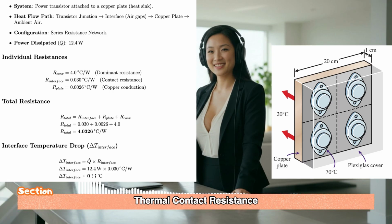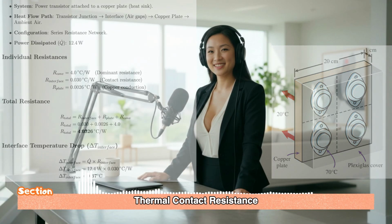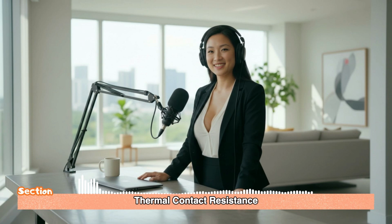But look internally. The interface resistance, 0.030, is still over 10 times greater than the resistance of the entire copper plate. And if the total heat flow is, say, 12.4 watts, that interface resistance alone causes a temperature jump of 0.37 degrees. That seemingly small temperature jump located right where the heat is being generated can be the difference between that component operating reliably and burning out. That's right. So even if our interface isn't the overall system bottleneck, it's absolutely critical for component-level design.